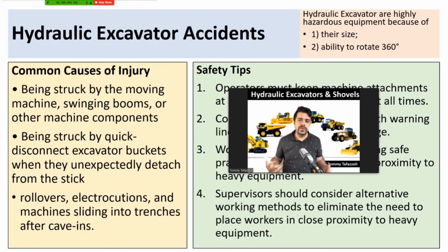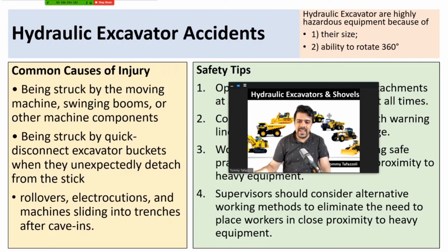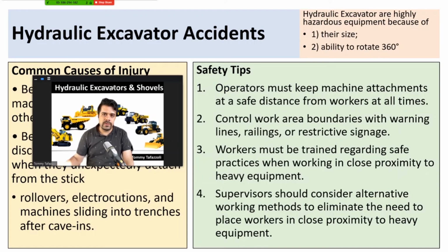So what should we do to prevent these things? Number one, the operator must keep machine attachments at a safe distance from workers at all times. As you can imagine, working with an excavator is particularly more hazardous in a congested work site, okay? That's why when you have the excavator, you should make sure that you don't have a lot of workers around.